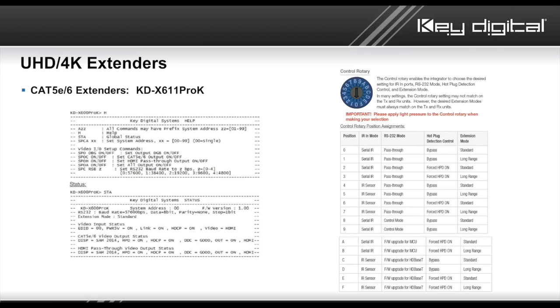We're the guys that get the call when tech support happens. It's not likely you're going to get some high-end HDMI knowledge by calling a big box company. So we sent the on command, and it didn't even do so much as make a picture loss if you sent it twice. If the video was up and running and you sent on again, so the customer put it in all of his macros, problem solved.